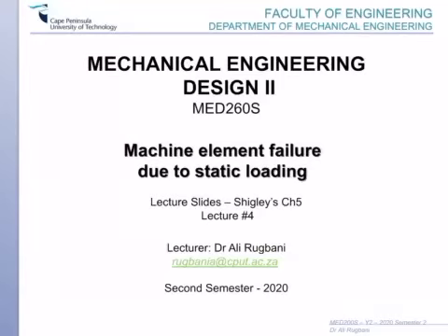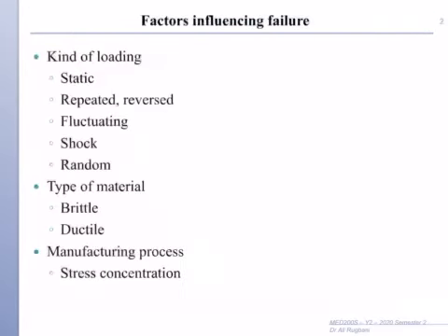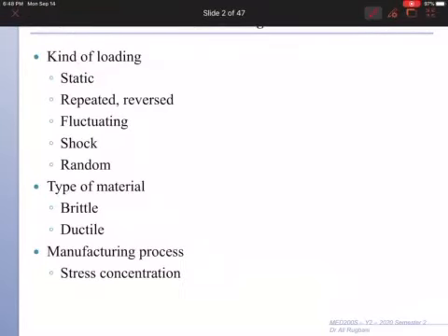In this lecture, we will look at machine failure and how to use stress in order to do static loading failure analysis. In studying failure analysis, we first look at the kind of load, and the kind of load can either be static, which is the topic of this lecture, or variable load that can be repeated, fluctuating, shock, and random load, any changing load. So in this lecture, we will only talk about load that doesn't change, doesn't increase, doesn't decrease, doesn't change point of action.